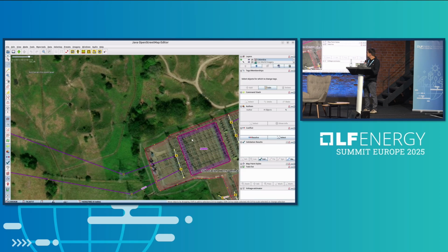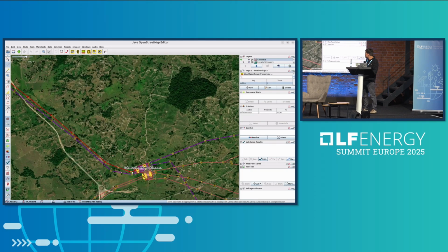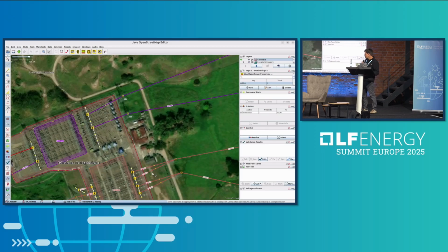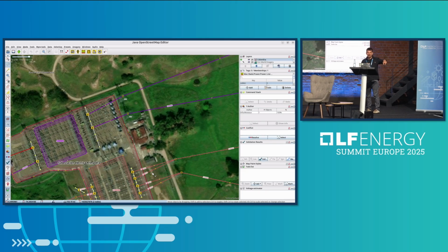There should be multiple circuits, and you see it in this case. One way we validate the data, sometimes, on the number of circuits is just looking at the shadow of the power towers. You can just count the number of cables in it. That's actually no problem to do. If you have multiple circuits, then you always see that at the end the circuits get split up, and then end at two portals. And you can see that. That's the interesting thing. So you can calculate and validate again the number of circuits on this line.